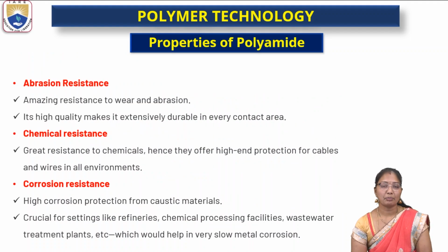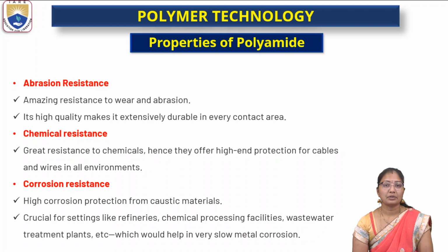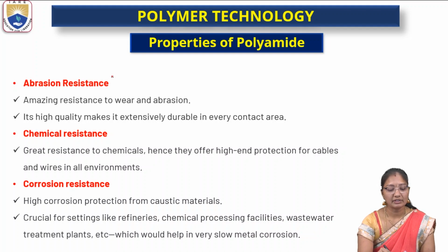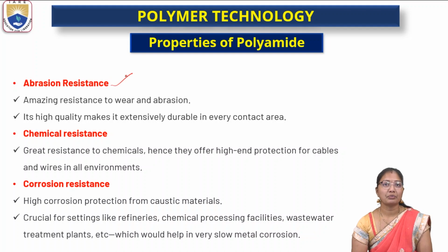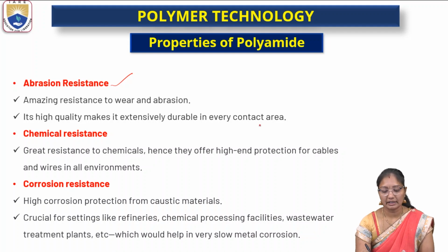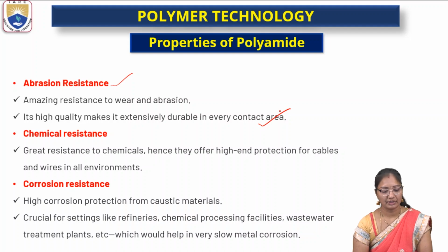Now, the properties of polyamides. They have very varied and vital properties, and they are now used at the industrial level. The applications of polyamides are many because of their high tensile properties, abrasion resistance and resistance to wear. This high quality makes them extremely durable in all contact areas used in industries. They also have great chemical resistance and are very chemically inert. They won't react with the chemicals present in the surroundings or in contact with the surface of these polymers.